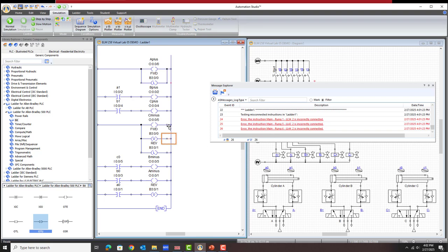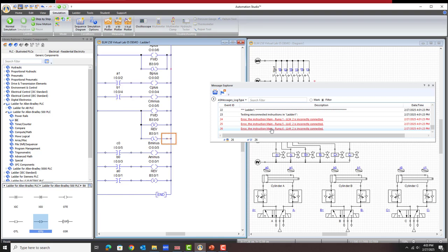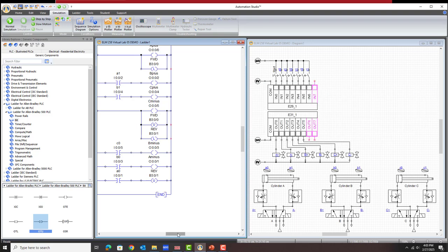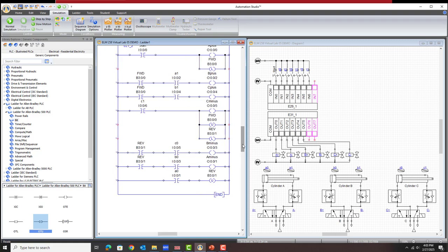Anytime you have this parallel, you actually have to run it up here, so there's only two connections on either end of the power to the power rails. I call this power rails. That's what they're called. They're virtual power rails. It's kind of like reflecting a hardwired logic diagram. But all right, so let's just make that correction, and we're done with this. And I think that will do the trick.